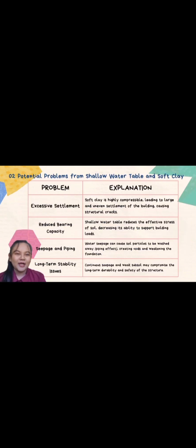The site has a shallow water table and soft clay beneath the foundations, which can cause several issues. First, the soft clay is highly compressible, which can lead to uneven settlement and cracks in the structure. Second, the shallow water table reduces the soil's bearing capacity, making it harder for the ground to support the building. Third, water seepage can wash away soil particles, a process called piping, creating voids and weakening the foundations. Lastly, these issues together can lead to long-term stability problems for the building.